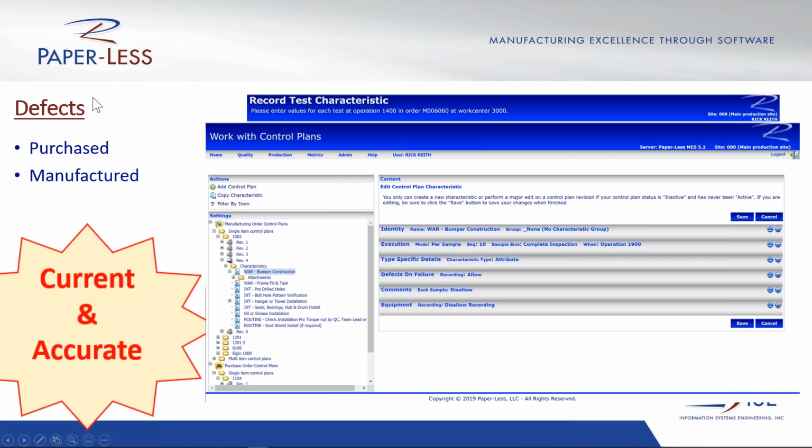Again, overlapping a lot of different categories for the 8 forms of waste in lean manufacturing, where you're wasting steps in motion, you're actually having excess production or over processing because I have to do rework, or I have to buy more parts, or I have to make or manufacture or release an order to manufacture more parts because my yield is not 100%. It's at maybe 60, 70, 80%. So a lot of things can be taken away by understanding where my defects reside and finding those as early in the process as possible.